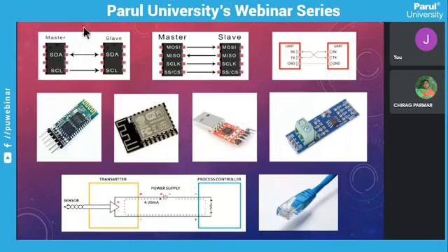So this is the example of an I2C communication. There are two ICs, master and slave. This is a controller, and this is an external ADC or flash device or EEPROM, DAC mainly. It's a two-wire communication. The first is the SDA, through which the data is exchanged, and the second is the clock. The master gives the clock to the slave, and the slave latches the data according to the clock, and that's how the communication is done.